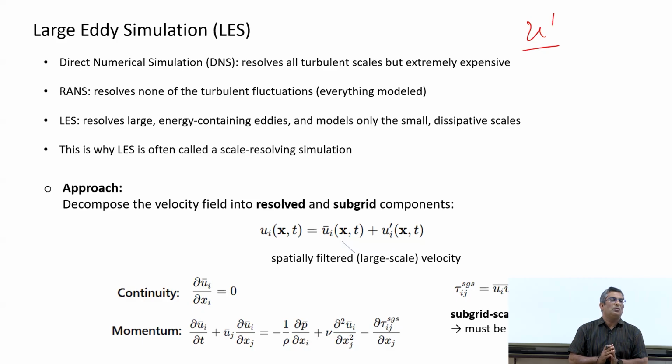So basically, you model for all turbulent eddies, because it assumes that you have only u dash that represents turbulence. However, from Kolmogorov hypothesis, we know that that is not the case. Here itself, when we say u dash, it contains the large scale eddies, the intermediate eddies, and the small scale eddies also. So RANS is blind to this division.